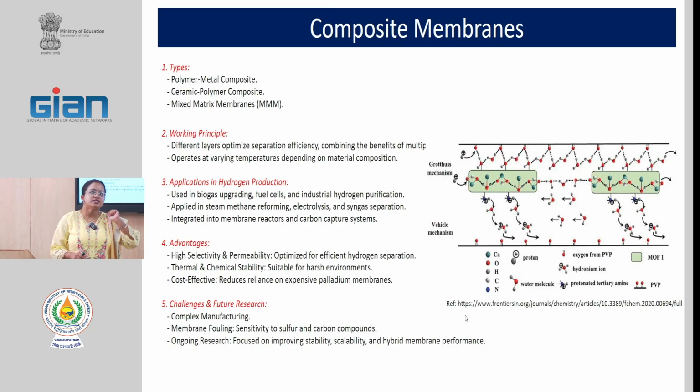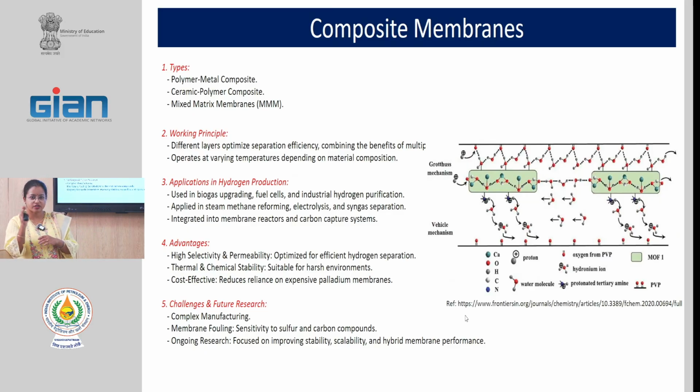Even throughout the membrane thickness, I can selectively concentrate some inorganic material towards one side. Let us say I am concentrating some palladium nanoparticles towards one side of my polymeric membrane, so that they offer sensitivity towards hydrogen transport through the membrane. Based on the gradient of mass transfer and the gradient of potential, you can decide which way to concentrate your inorganic material more.